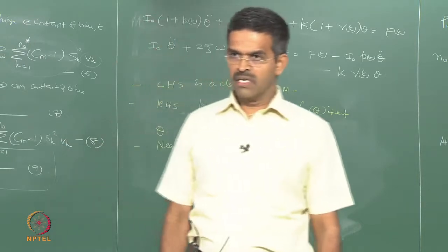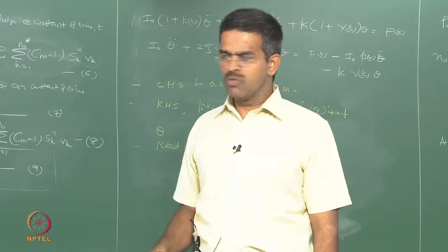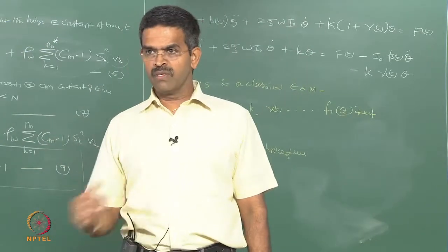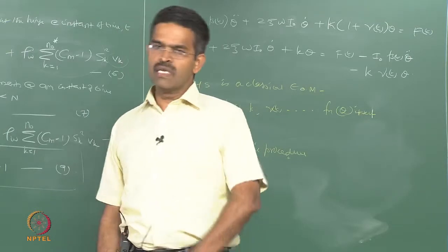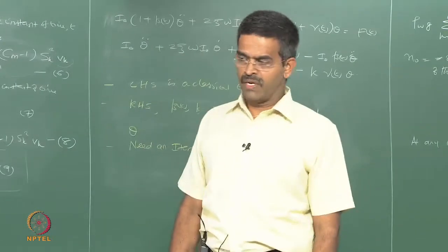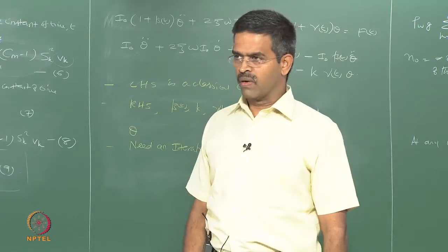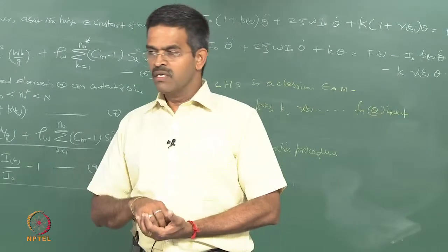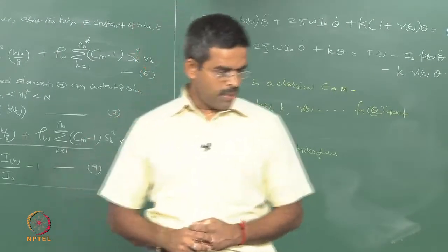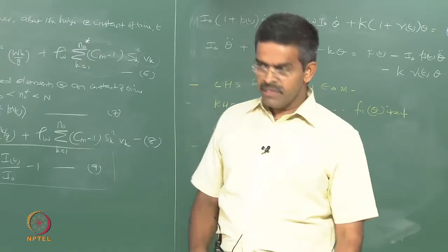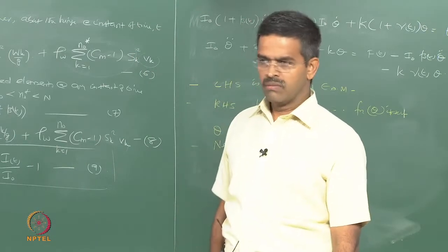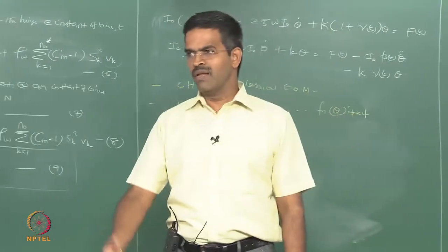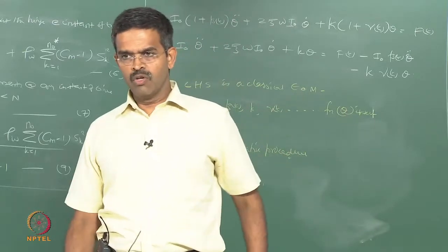More and most interestingly, since you are connecting the tower to the seabed using a universal joint, the bending moments in these joints are practically 0. So the design of the foundation of the system becomes simpler, whereas in earlier cases the design of the foundation becomes very severe and very difficult, okay, pull out etc. But in this case the foundation becomes very easy, because the moment at the joint at the seabed is practically 0, because we all know that the bending moment at a hinged connection is practically close to 0. But there will be some moment, okay, as I showed you in the M5 curve, but that is an initial value, otherwise it is practically 0 for design considerations.